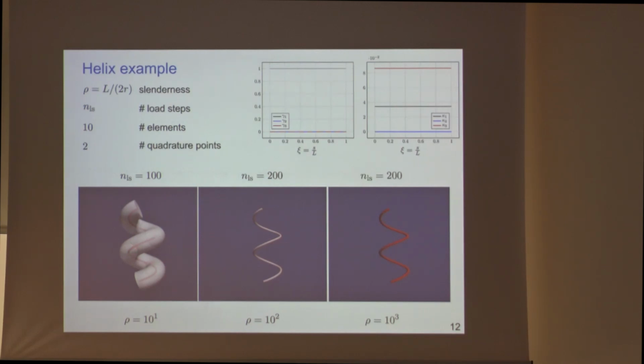So it is actually not a very good benchmark example, because you will get the exact solution even with the interpolation. But also all other benchmark examples are passed quite well. Also, if you have non-constant strains along the beam, then certainly because you have constant strains, you need a higher resolution if you're really interested in the strain distribution. Otherwise, if you are more interested in the displacement, then a coarser resolution is fine as well.